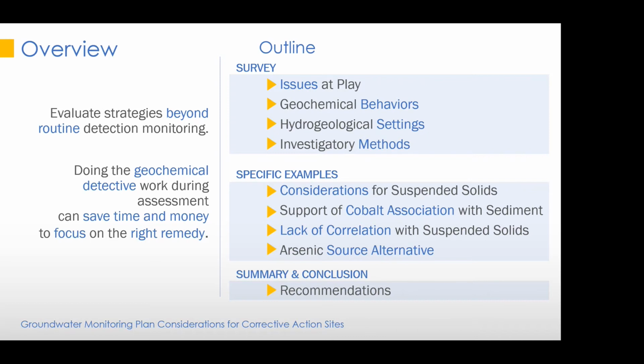And the third issue with this is that these chemicals that are in Appendix 3 and 4 are metals and cations and anions that occur naturally. And so the alarm system itself can generate, and is in fact statistically designed to generate, false alarms, false positives. So in order to keep the false positives from triggering bigger issues, we can use some strategies from geochemistry to understand what's going on.